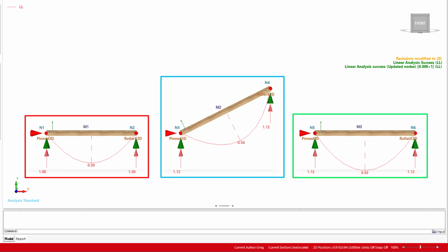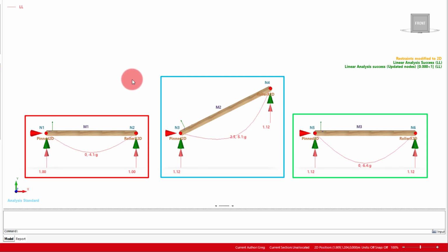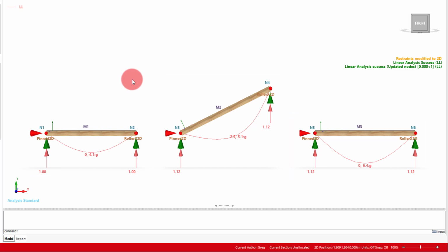We also look at our deflection. Just considering the vertical component, it is also conservative. So when using the incline function, you'll need to be aware that it is a simple approach that can be conservative. As a side note, this typically won't be an issue for wind loads as they act perpendicular to the surface of the member. That about covers the incline function.